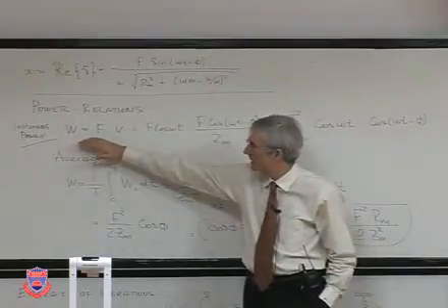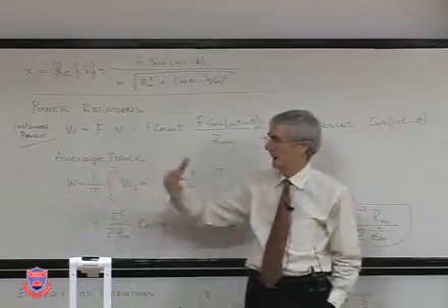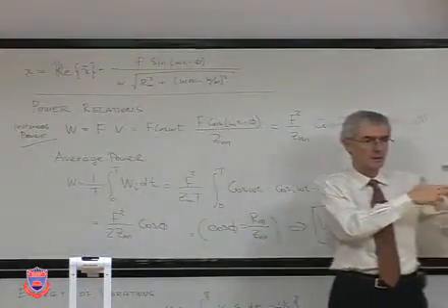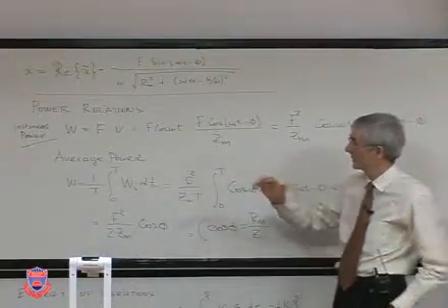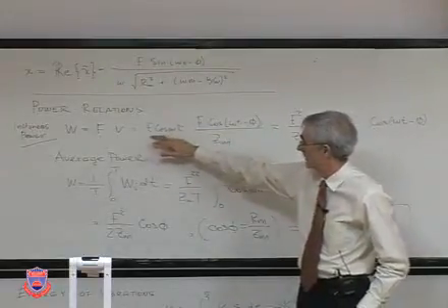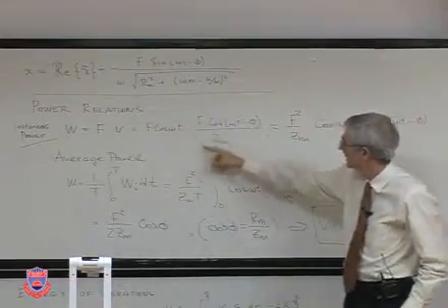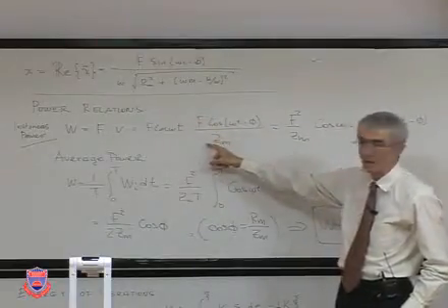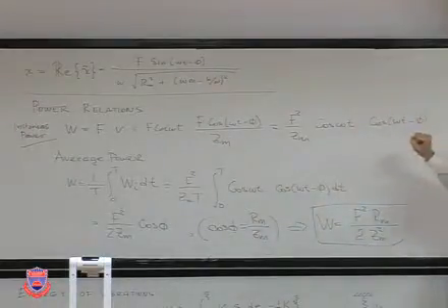We express the instantaneous power at a given time t as a product of the force and the velocity that it causes in a system. We're now considering the simple harmonic system, but this is true for all physical engineering systems. And force is an amplitude times its harmonic oscillation, and the velocity response is written again in terms of force and impedance, and we have this expression.